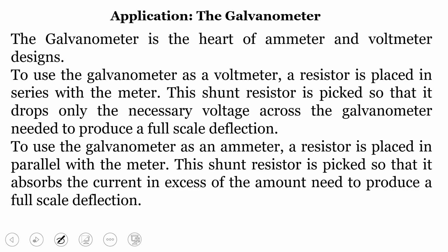So, with the knowledge of how current flows in resistors in parallel, you can determine what current flows through the other channel when tiny current flows through the galvanometer. And when you want it to act as a voltmeter, voltmeters are connected in parallel to our circuits. If you recall from the first circuit we had when we were discussing Ohm's law, the voltmeter was connected in parallel.